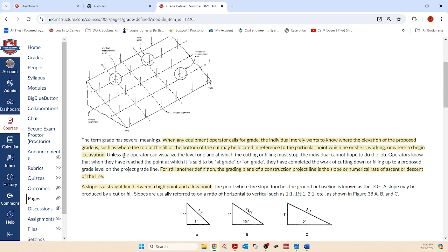As I said before, slopes are usually used where there's a lot of work to be done. Percent grade is used on smaller operations, like I said, of laying a sewer line or stormwater drainage from catch basin to catch basin. None of those things actually are level. They're all falling in different directions, or rising if you're looking the other way.